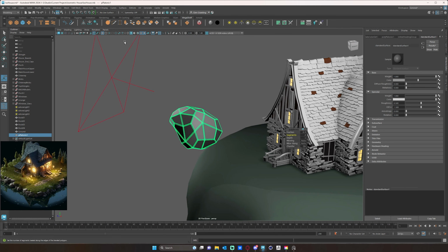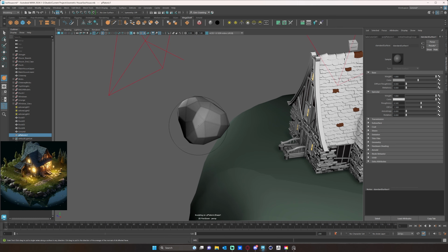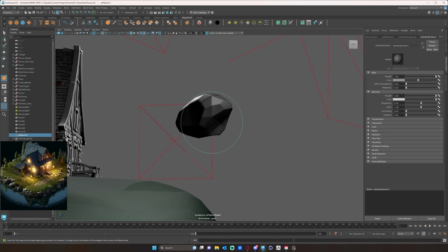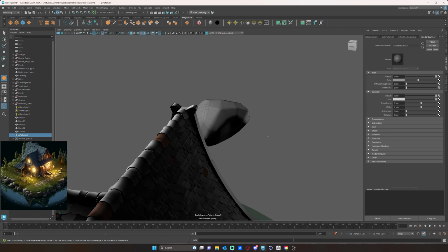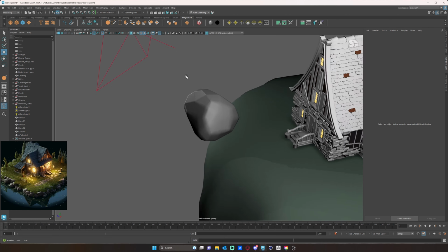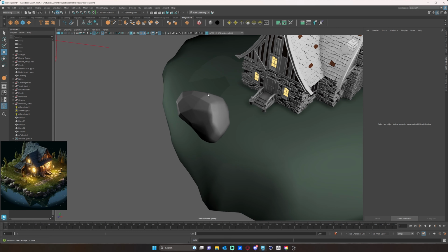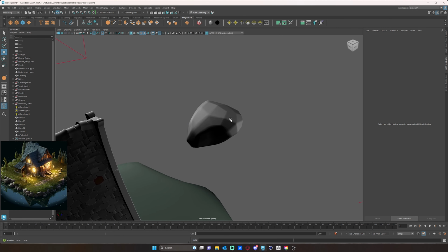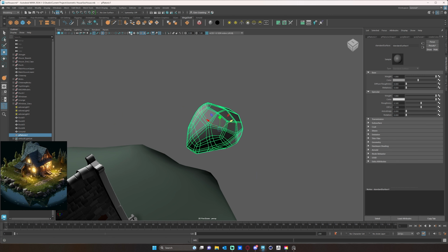But then I can hit it once more with my sculpt tool, holding down shift, just to smooth things out, very lightly tapping it here and there. And then you'll get something that looks a little bit more like a natural rock, where some of it's round and smooth, and then some of it has these really sharp, faceted faces.